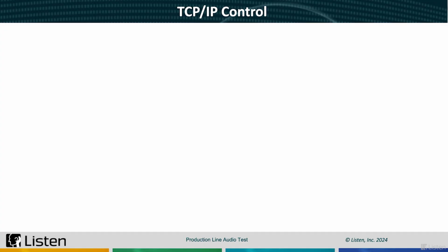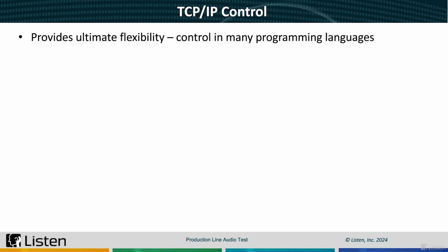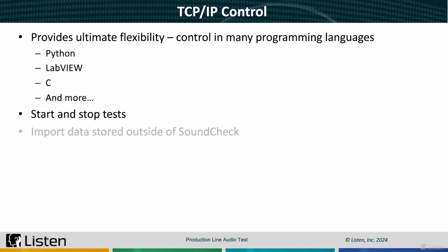Since SoundCheck 15, we've also included TCP/IP control. This provides ultimate flexibility, as you can control it in any programming language that can provide TCP/IP commands, such as Python, LabVIEW, C, and more. These commands may not only start and stop tests, but also import data stored outside of SoundCheck.